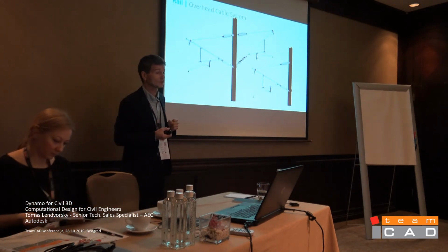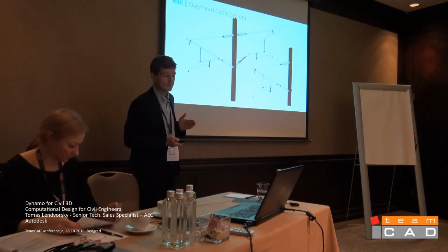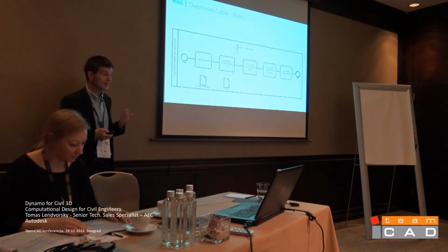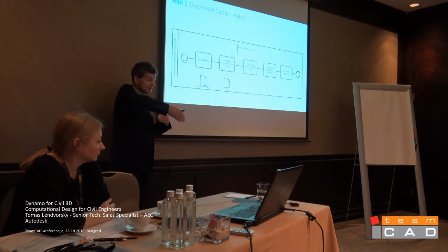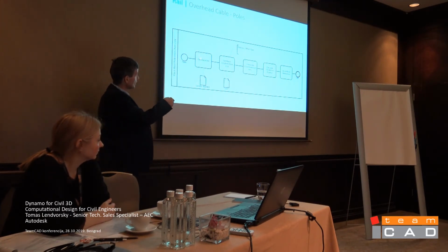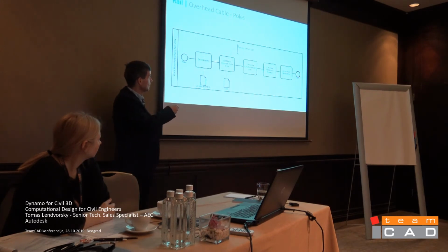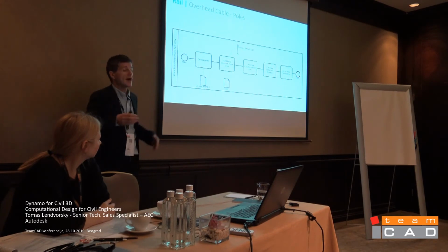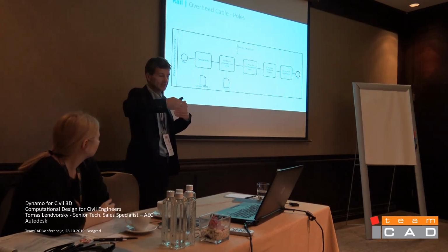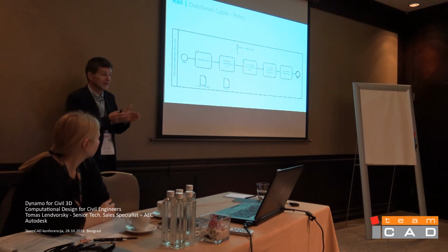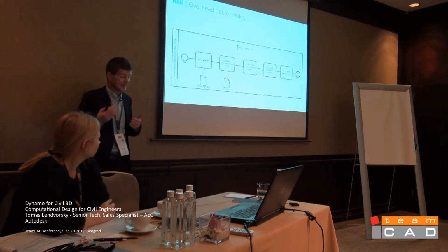Kind of similar, if you want to make an overhead cable system, because these are discrete information, and you want to place them in the system. This is an example which maybe is not at some regular interval. First you will get information about the corridor. You need to know where your corridor is and what the profile is, so you will get the baseline. But then you have the possibility to read an Excel sheet or CSV file that will state where these locations are, in which station interval you want to put them. There can also be written how far it will be from the center line. All this information you can get from this external file.